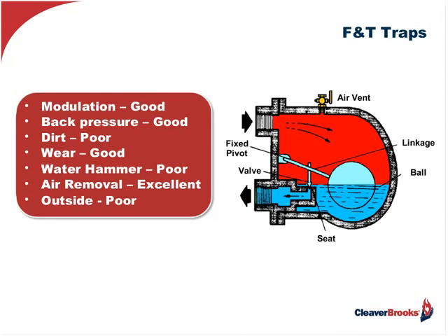Modulation, good. Modulating loads. Back pressure, good. Dirt, poor. Well, I don't have to read these all. You can read them yourselves. But water hammer, obviously, because of the float here, can be quite damaging to this particular trap. So if you get into a lot of water hammer type situations or possibilities, this would not be the best trap to be using. Air removal is excellent. Outside, poor relative to a thermodynamic.